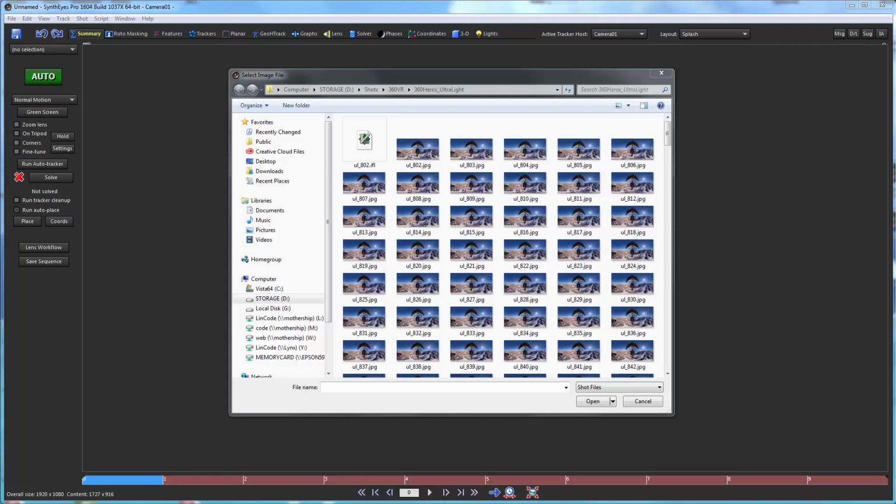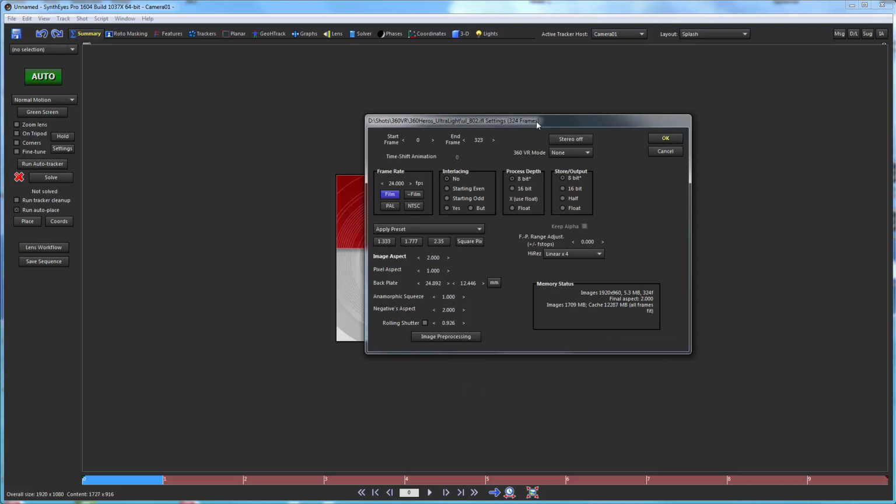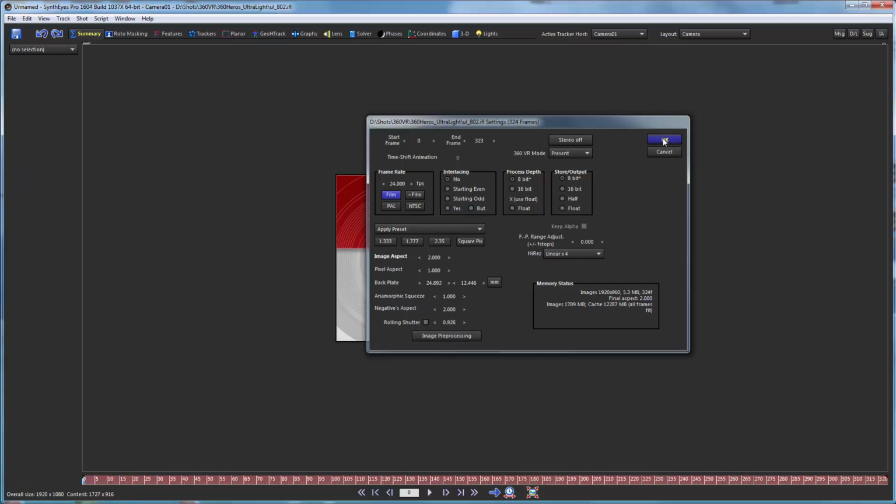This is Russ Andersson. In the second part of our tutorial, we're going to take a look at the initial linear mode tracking of our 360 VR scene. So we're going to start by opening up the shot. And one key point here is that we want to mark that it is in fact a 360 VR shot. You'll notice there's also a remove option that'll be used automatically by some of the scripts later. And it can also be set manually, of course, too.